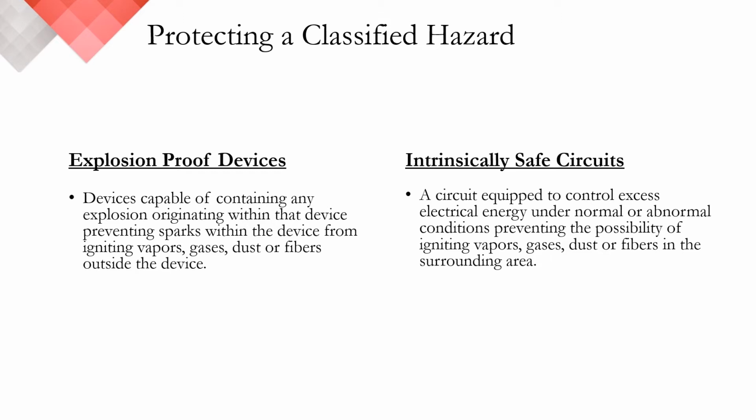Often when I'm speaking to people on this subject, the methods of explosion-proof almost sometimes get intertwined with the method of intrinsic safety. So this part of the webinar is really about defining how Protectowire is listed in a classified hazard and the steps that we take for you to follow to ensure the listing. And on the next slide, I'd like to talk about the intrinsically safe barriers that we install here at Protectowire in our control equipment to create the intrinsically safe circuitry.